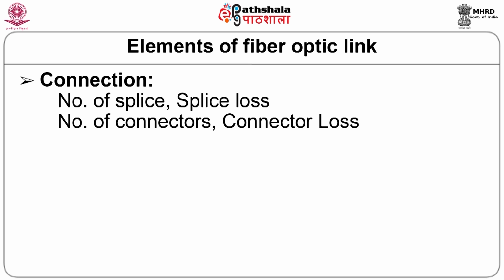So the splice loss is also important when we have a connection. How many connectors are there? Connectors mean coupling the source with the optical fiber. There we require some connectors. So what is the connector loss associated with it? That is also important when we consider the connection.